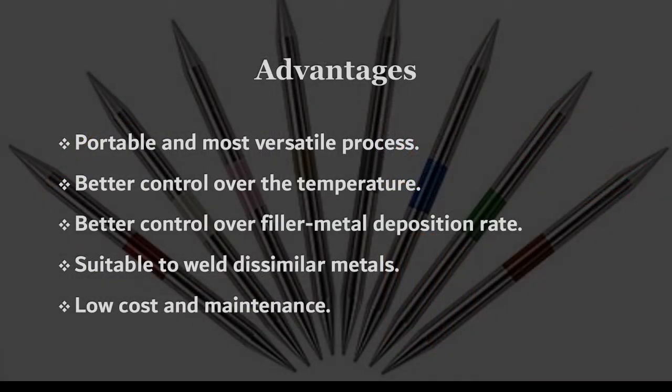There are several advantages of oxy-fuel gas welding. The first is that it is a portable and most versatile process. The next, better control over the temperature. Then, better control over filler metal deposition rate. And it is suitable to weld dissimilar metals. And the last is low cost and maintenance.